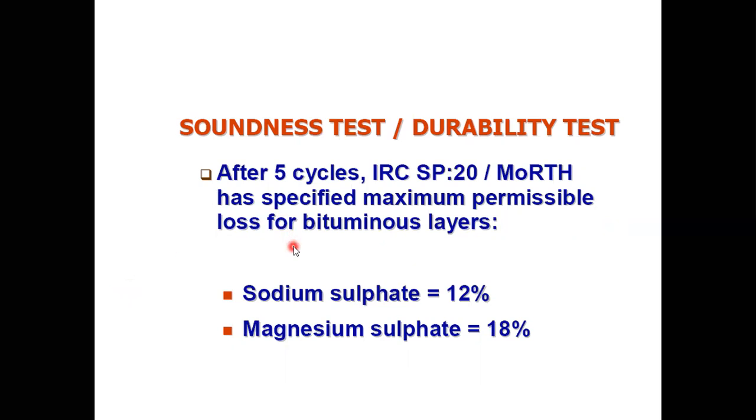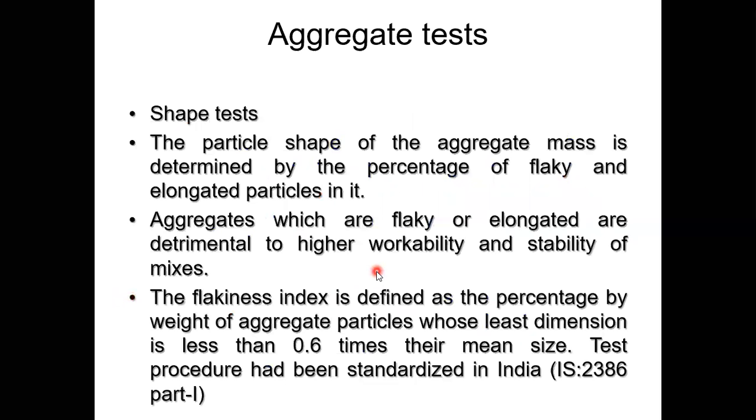You're going to take the aggregates and pass them through some chemicals, sodium sulfate, magnesium sulfate. After 5 cycles, you'll see how much percentage of material is disintegrated. Okay? So it's okay. Yes, the proper procedure we will learn later.